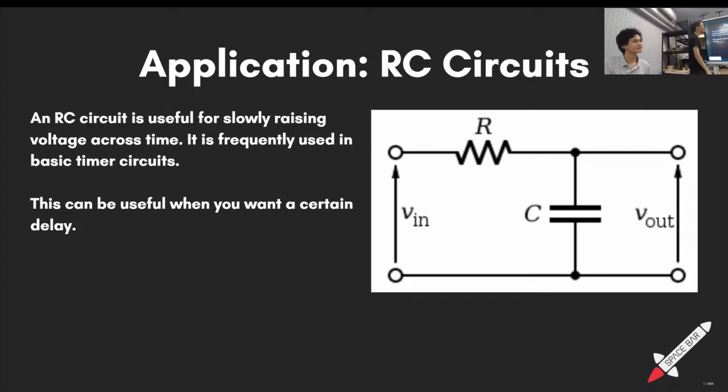Approximately, yeah. Wait, what does it do after going down to the capacitor? It goes through the resistor and then down to the capacitor. Okay, so initially the current flows through here and then it stops flowing, right? It stops flowing because the capacitor has reached V in here. So initially the capacitor is at 0. As it charges, the capacitor's V out increases. The voltage of the capacitor increases as it charges, which is delayed by the R.